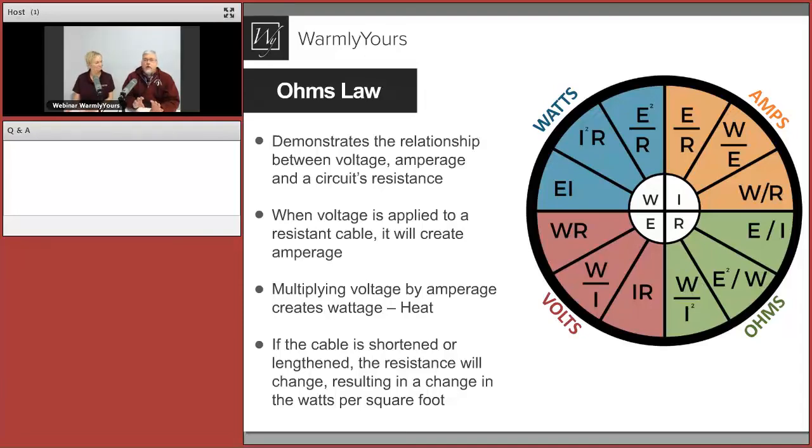We then work that combination with the amount of voltage you get. So we know that short mats have different watts per linear foot of the cable than really long mats do. That's why you can't just take a really long roll and cut it in half and put one half in one room and the other half in another room, because it will overheat.